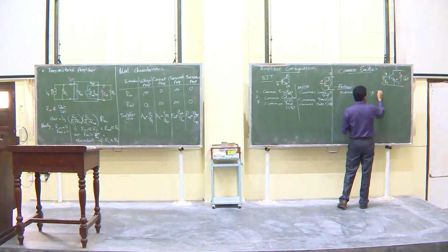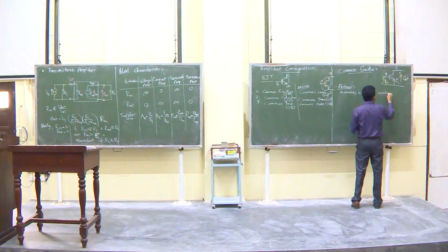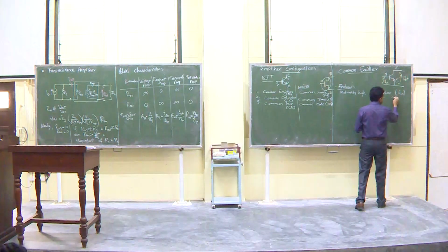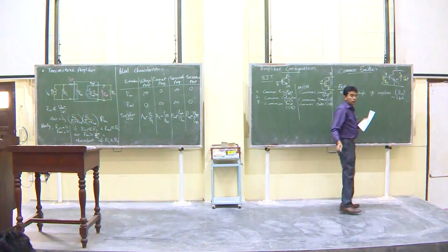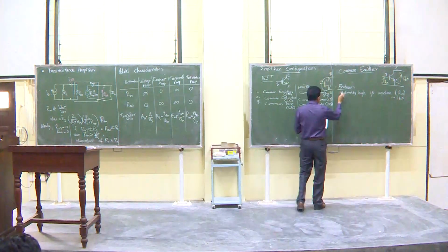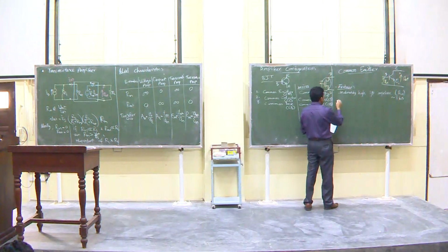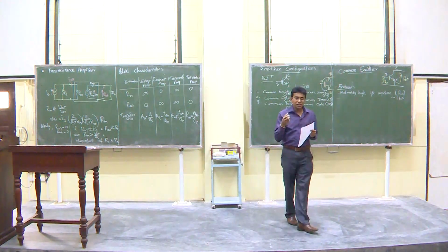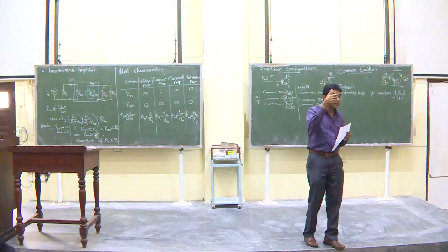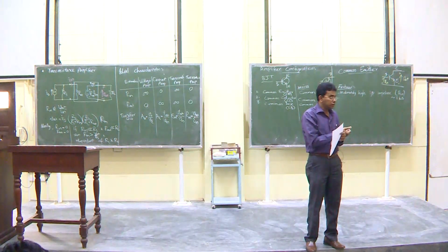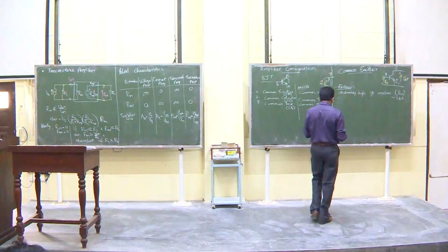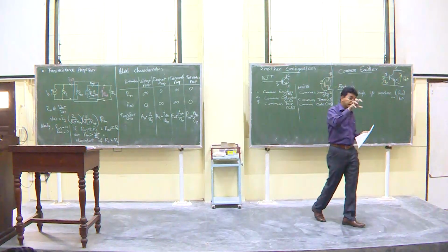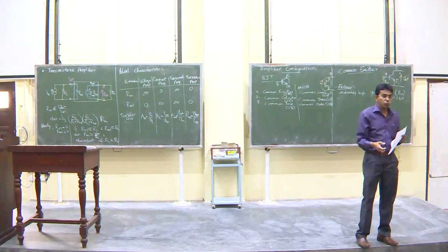input impedance, input resistance or impedance R in, right? So typically in the range of 1 kilo ohms. That's kind of the ballpark. Output impedance. Now, when we analyze the circuits, we will see that output impedance is actually the resistance RC that we connect to the circuit, right? If you look at an example, we'll have a look at it. So the value of the collector resistor that we put determines what the output impedance is.